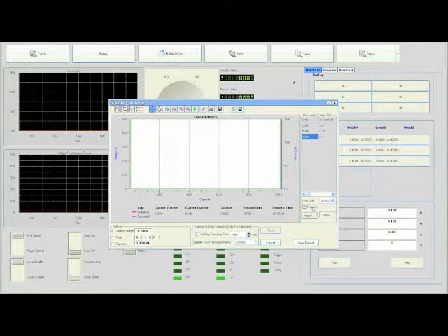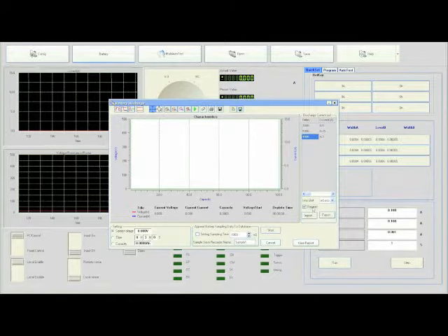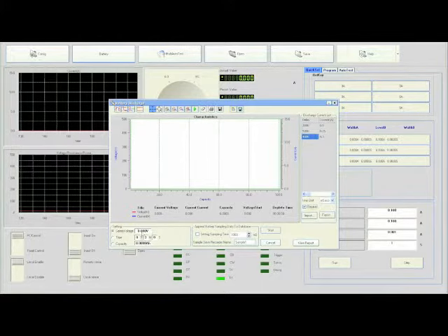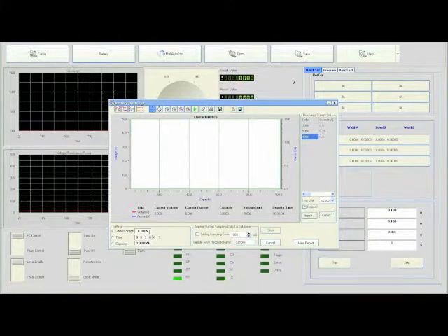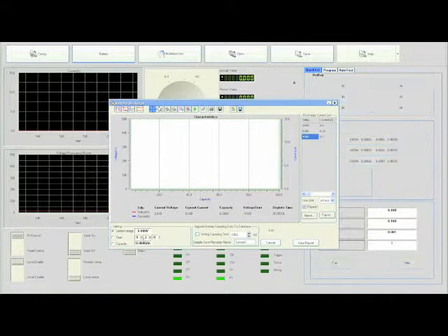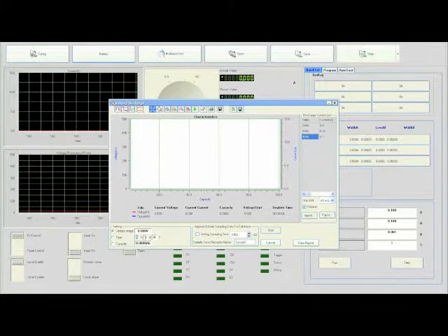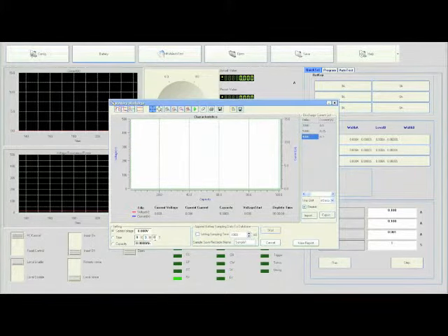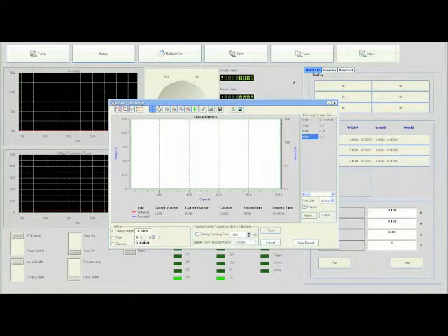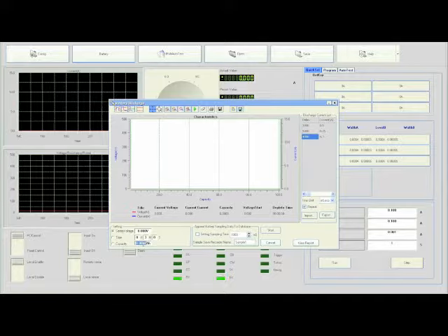The software gives the user the option to select how the test will be run. Users can run the test based on safety voltage or threshold voltage, similar to the internal battery test demonstrated earlier. Next option is to specify a specific amount of time to run the test. Users can enter hours, minutes, and seconds. Lastly, users can run the test based on a certain capacity. Once capacity is reached, the test will end.